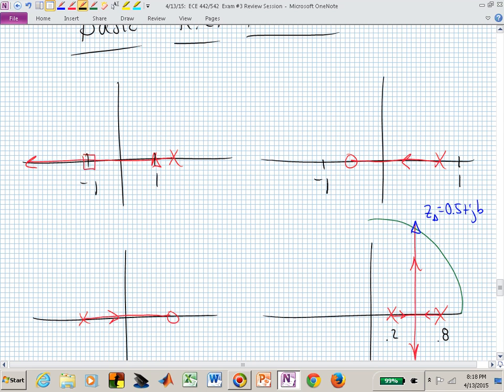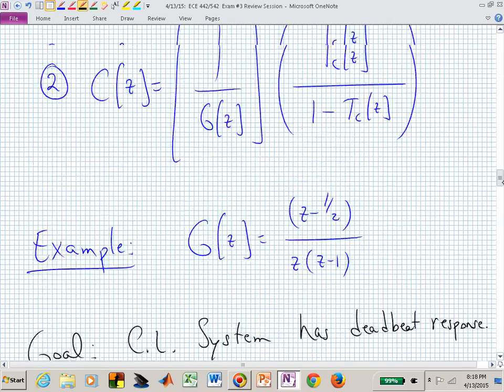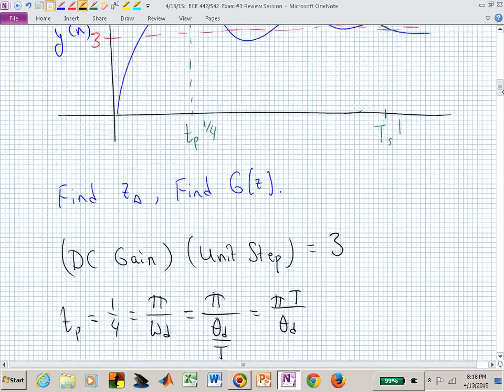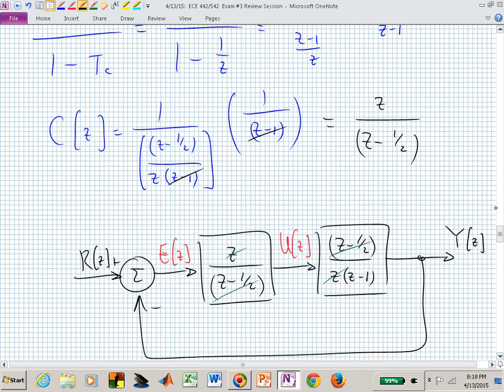So really when K is equal to 0, what I would suggest that you do to get a feel for what's going on is this. Let's say that now K is 0. You wouldn't have any transmission through that system, would you? So at K equals 0, think that you've disconnected the feedback, your controller is 1, and you now just have an open loop system. That's the concept or the idea with K equal to 0.